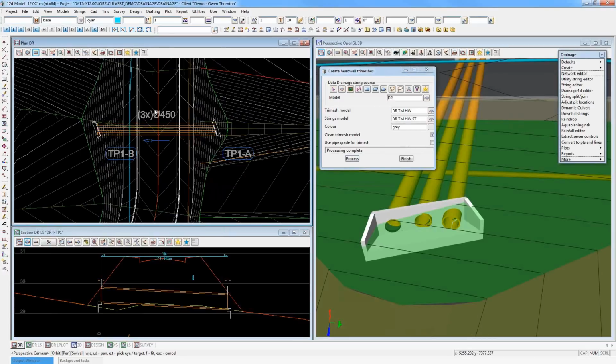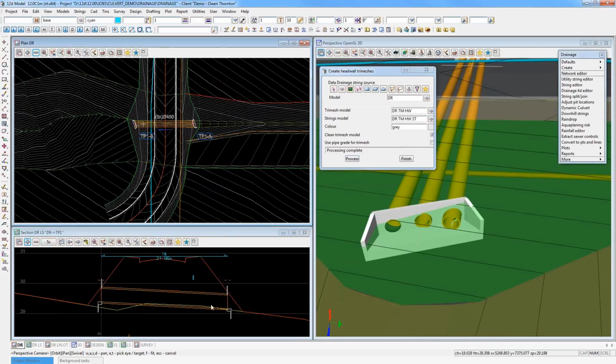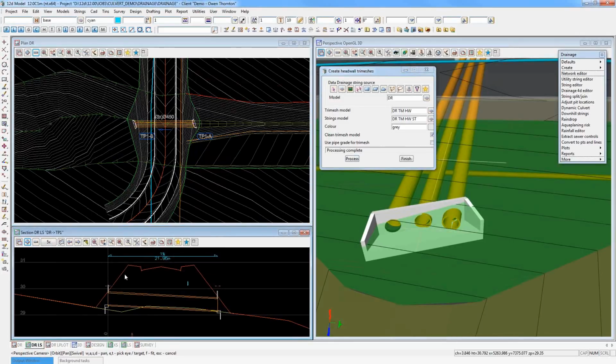fairly recently, actually, that some people have a convention for their culvert long sections, so that when they show the culvert here, they want the left-hand side of the road always to be on the left, so it's relative to the road direction. In this case, most stormwater designers always have their stormwater pipes falling from left to right, but these people were wanting a convention where it depended on the road direction, so that when they look at their culvert long sections, which is typically also a road cross section, they want the left-hand side of the road on the left and the right-hand side of the road on the right.